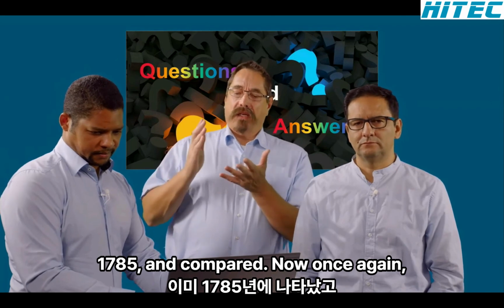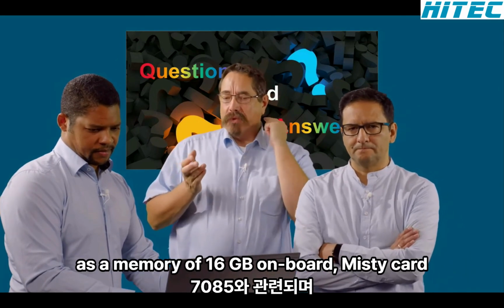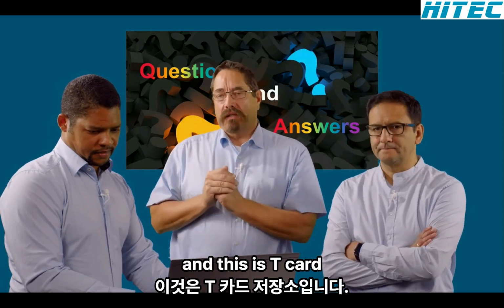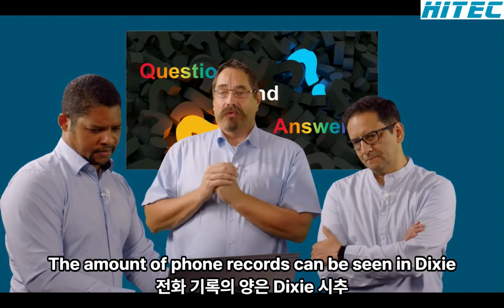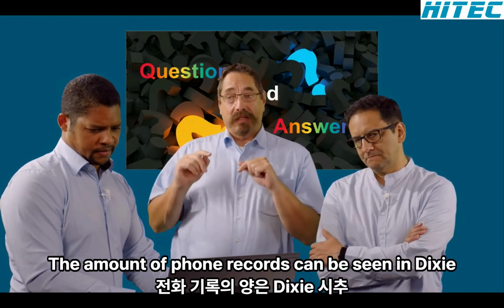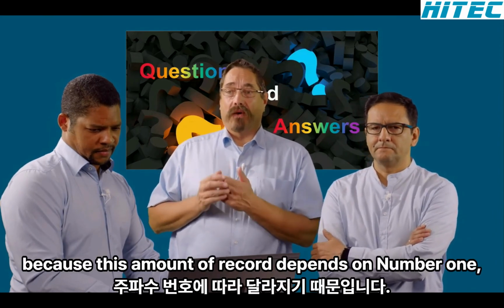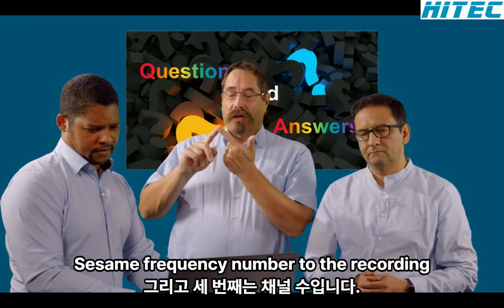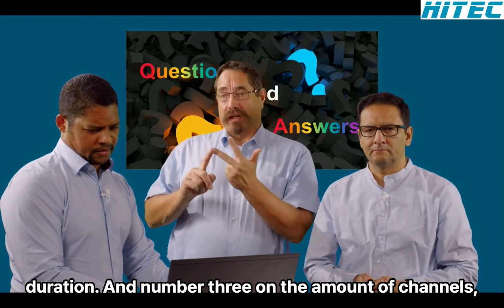And compared, once again, the 7KE85 with a protection relay, the 7KE85 has a memory of 16 gigabytes on board, the SD card. This SD card stores a lot of fault records. The amount of fault records can be seen in DIGSI during parameterization, because it depends on, number one, the sampling frequency, number two, the recording duration, and number three, the amount of channels.